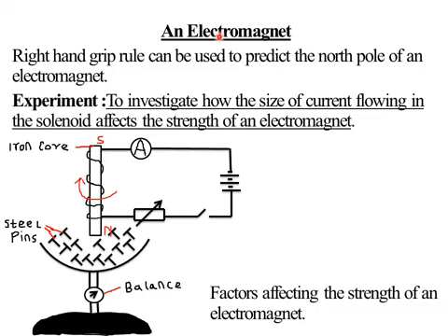Remember, direct current is denoted by DC. Whenever you pass a direct current through a magnetic material, and especially the soft iron core, because soft iron core can easily be magnetized and demagnetized. Because we want a material which can be magnetized faster, that's why we are using a soft iron core. So you simply pass a direct current in a soft iron core, then you will obtain your electromagnet. Then we are saying that an electromagnet is a temporary magnet.